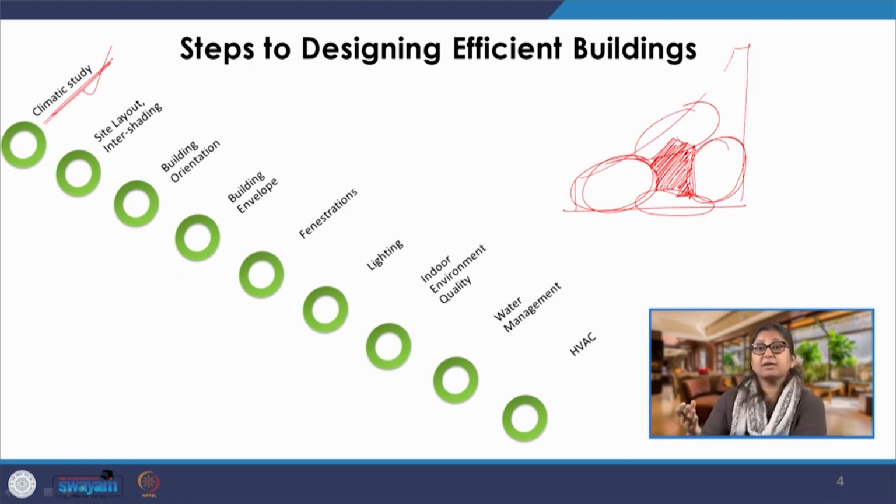And if you look at the traditional buildings which are there, if you look at the classic examples, we will see that difference being evidently clear. We have a different type of building for hot dry, we have a different type of building in warm humid. If you go to Kerala, you will find that the buildings have ample opportunity for air to be ventilated in, huge windows, verandas which cut off the rain, but allow the wind to move through in the spaces, and the buildings remain absolutely comfortable, narrow courtyards which allow ventilation to happen throughout the day and night.